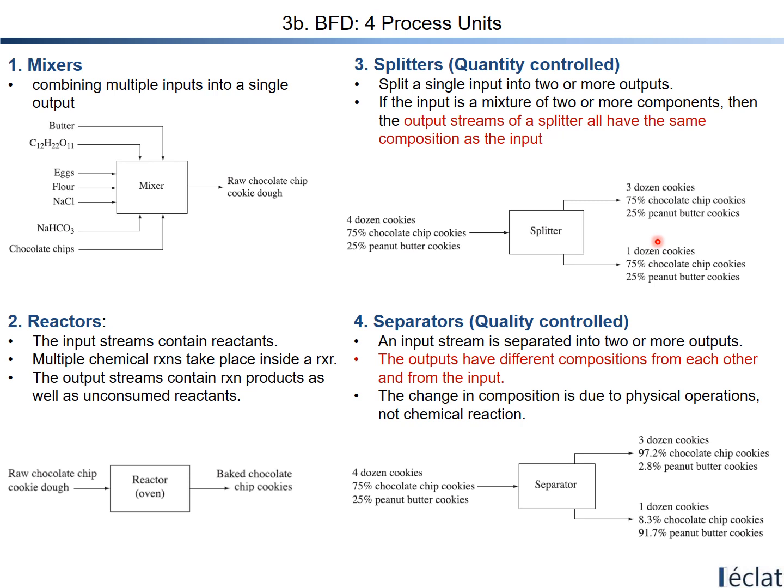So usually you should have multiple output streams, and typically only one single stream is introduced into the splitter. If the input is a mixture of two or more components, then the output streams of a splitter all have the same composition as the input. Okay, so here's an example.